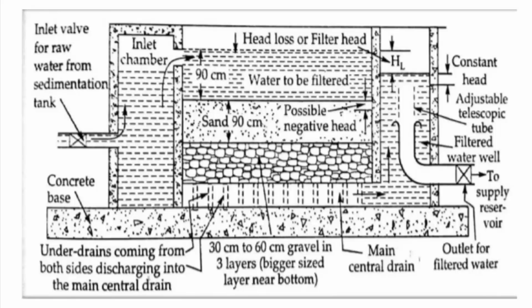Immediately after replacing this sand layer or filter media, we cannot restart this filtration tank, because the dirty skin or the filtration enhancing agents will not be present in this sand layer. That is, the bacteria, the sedimentation mechanism, and the biological mechanism will not happen at this stage. The purely cleaned filter media will not support these mechanisms.